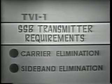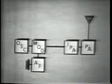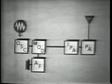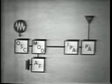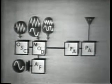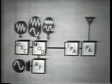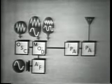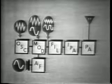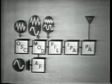and now let's take a look at the way this is done. Looking at the simplified block diagram of a conventional AM transmitter, let's change it to operate single sideband. Of course, we use a crystal oscillator of low frequency RF to generate a stable carrier. When we modulate it with an audio frequency, the two signals are mixed together in a balanced modulator, which is designed to cancel out the carrier and filter the modulating frequency in its output and produce only the two sidebands, the upper and the lower. We then insert a filter which will pass only one of the sidebands, and of course we can select either one, and we'll reject the other one. Thus we have only one sideband to be transmitted with all of the transmitter's power.